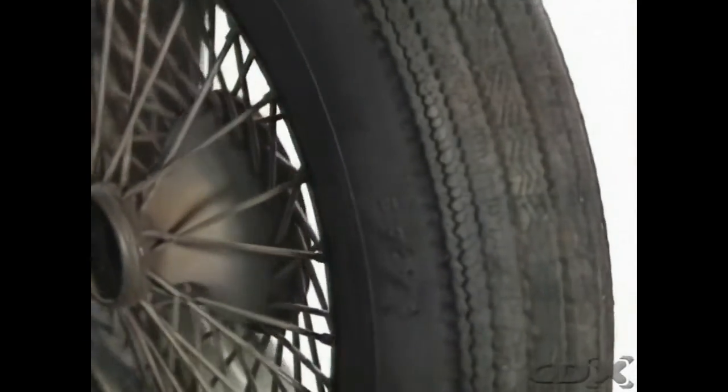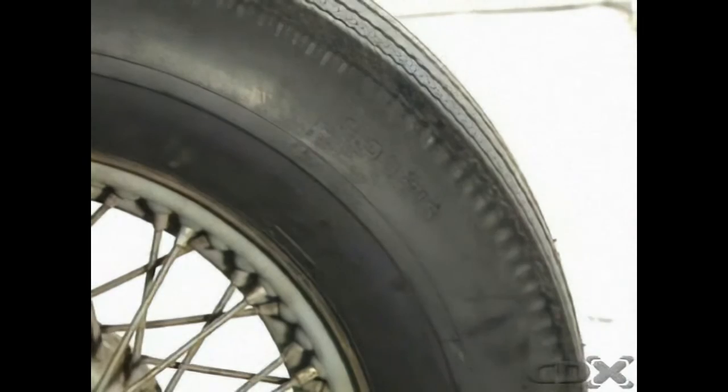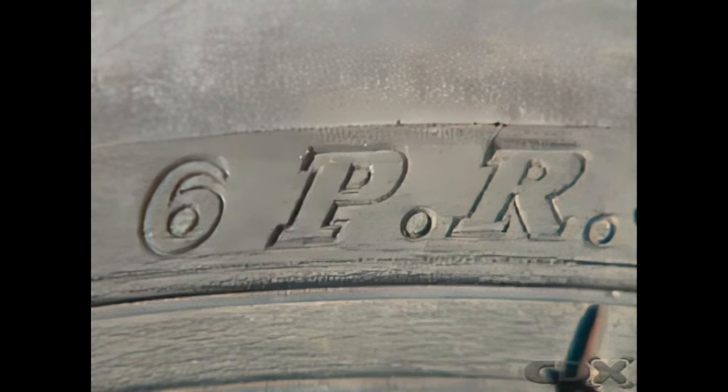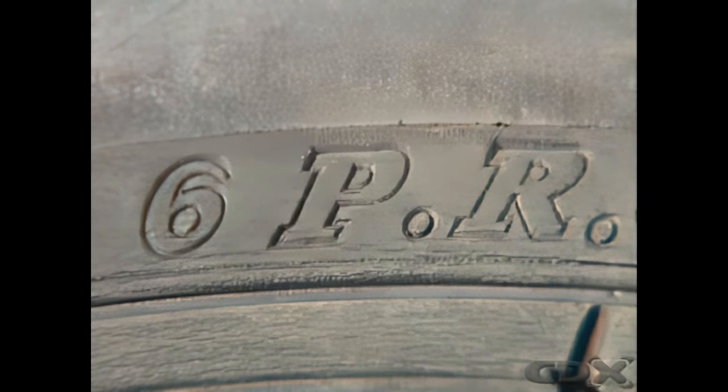All manufacturers mold information about the tire into its sidewall. In cross-ply tires, the bead diameter and the section width are stated in inches. For example, 600 by 16 indicates a tire with a section width of 6 inches and a bead diameter suitable for fitting to a rim which is 16 inches in diameter across the bead seats. The load capacity is indicated by the ply rating, for example, 6 PR.